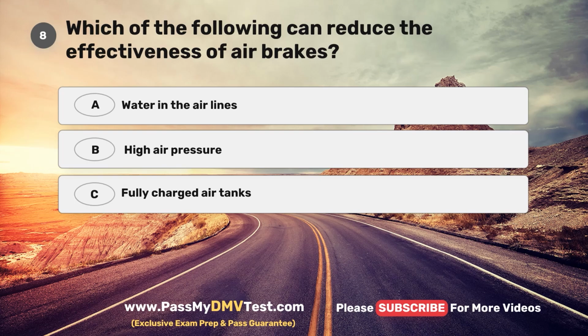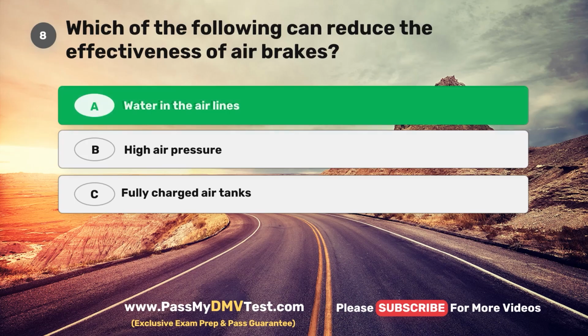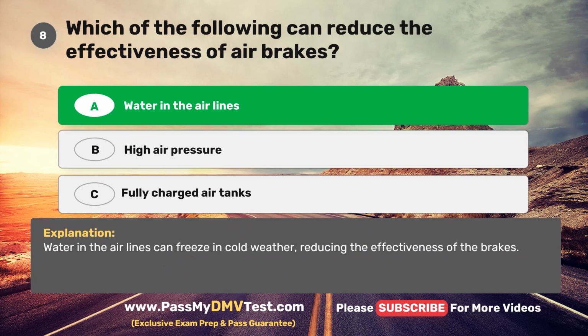Question 8. Which of the following can reduce the effectiveness of air brakes? A. Water in the airlines. B. High air pressure. C. Fully charged air tanks. The correct answer is A. Water in the airlines. Water in the airlines can freeze in cold weather, reducing the effectiveness of the brakes.